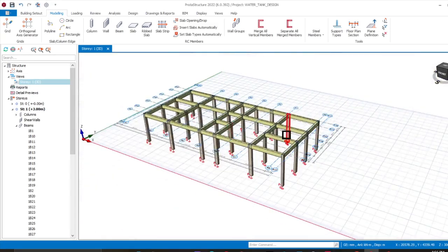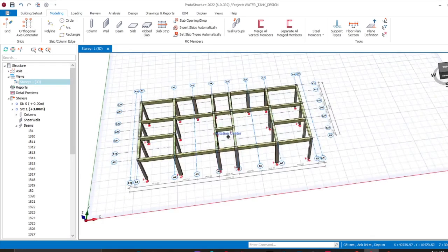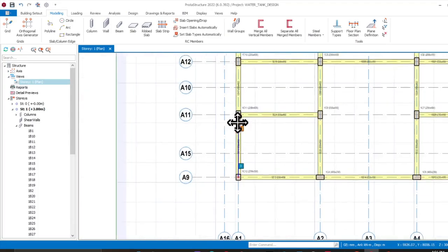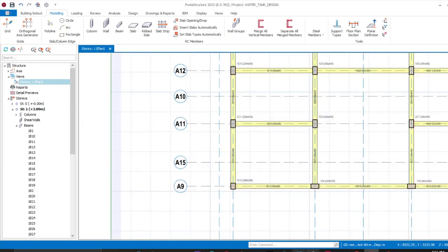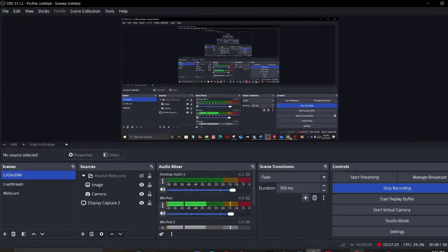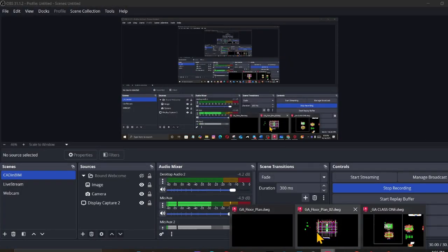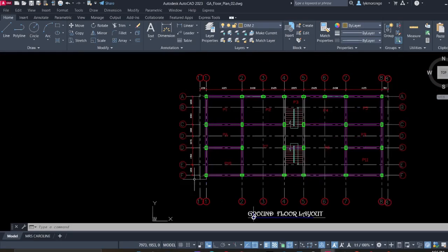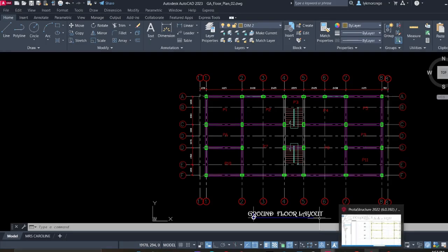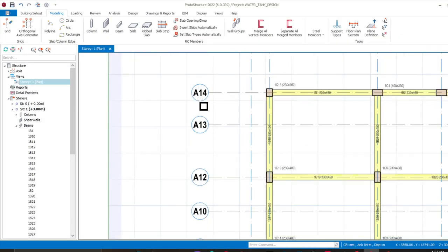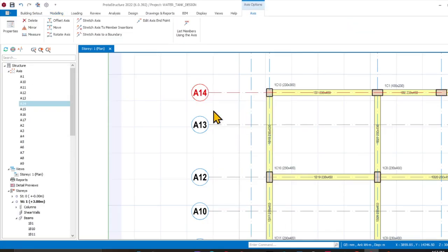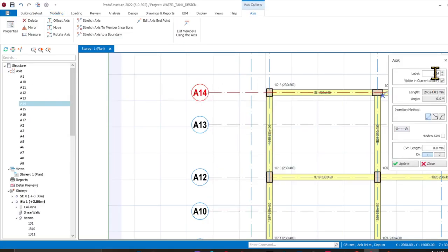So this is the model that you want to work on, and maybe one thing that you haven't done is actually to name our columns, our grids, so that we actually look as they are supposed. As you can see, our grids here, they are properly numbered. This is 1 to 8 prime, and this is A to F. So to proceed with that type of numbering, you can simply come to our labeling here, and then you simply come here, right click, this is A, just right click on this, change this one to just say A,